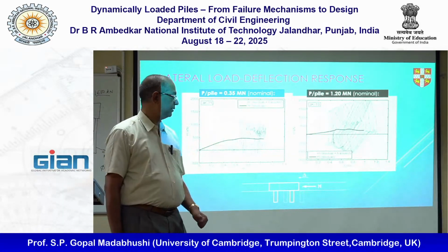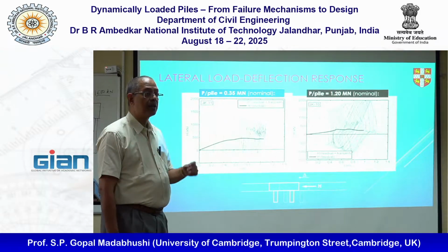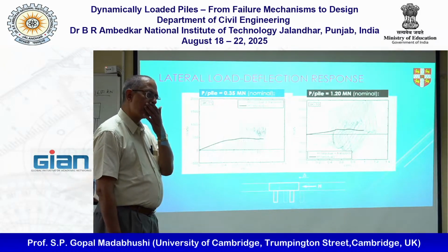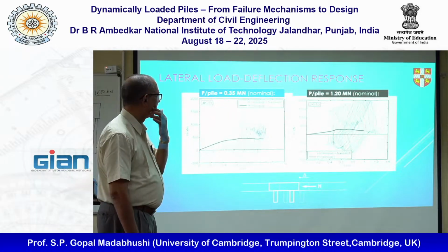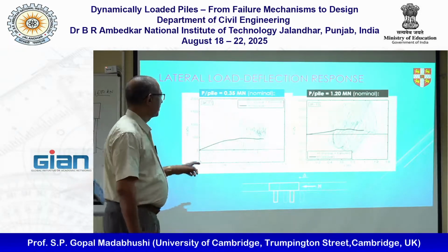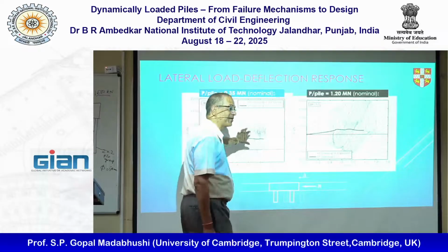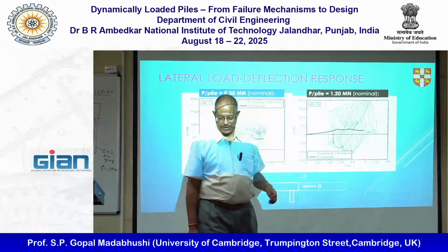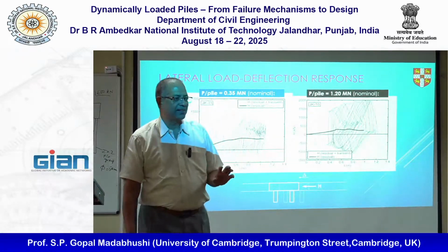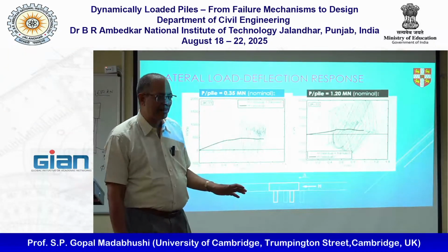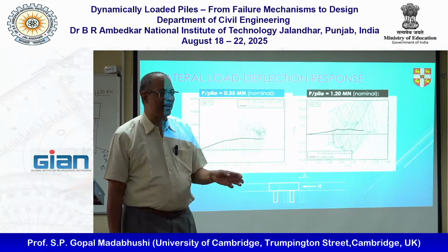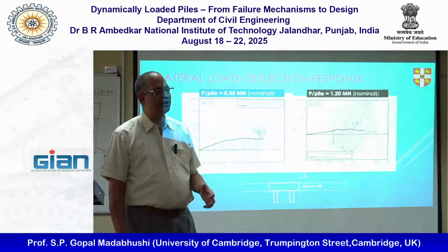Yeah. So in this, if we are having more extra load, it is not getting soft. More extra load is showing it is not softening. Basically, what it's showing is if you put so much axial load on the pile, no matter what the clay does, everything is dominated by the load on the top.